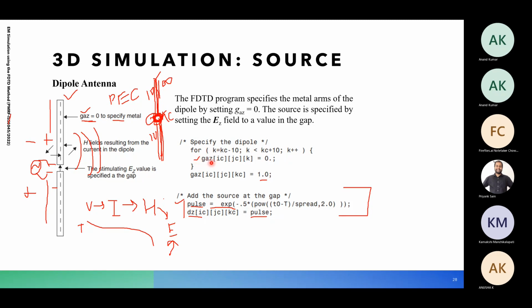But for example, what if we wanted a horn antenna or a more complex helical antenna or something like that? You'll have to write more complex code, but again, you'll be using the same concepts. You'll have one excitation near the two metal points of the antenna, and your metal structure will become more complex, but you will be using one point source near the excitation of this antenna.